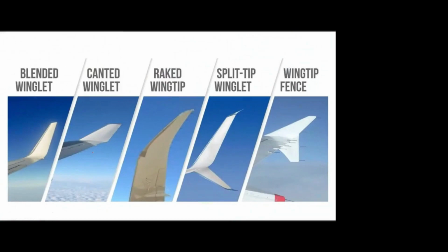And these are all the types of winglets. The first one is blended, where the wing itself is deflected upward, the curved one. This is the canted one. There is a small portion at the bottom also. And this is the raked one, the raked wingtip. Nowadays, all the new aircraft use this type of raked wingtip. It is inspired by seabirds, seagulls, albatross, etc. In older aircraft, you can see the blended, canted, split, etc. So the ultimate purpose is to stop the side leakage flow.